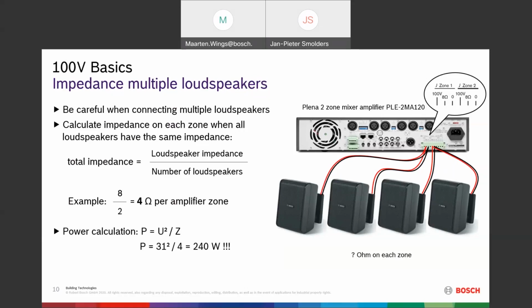So be careful there. If you add multiple low impedance loudspeakers to a single amplifier channel, be careful and calculate what the exact impedance is that you connect to this channel. So keep that in mind.